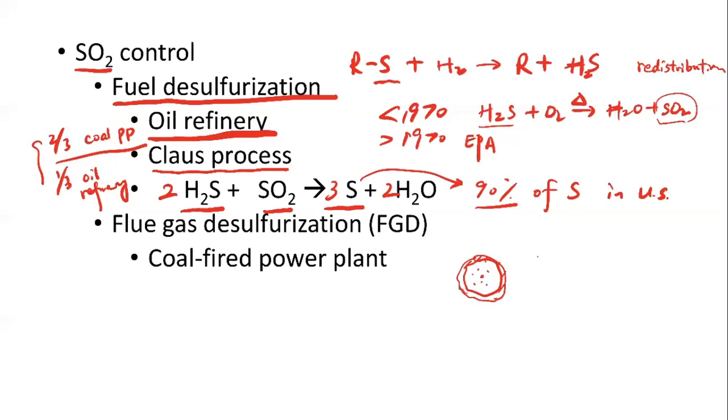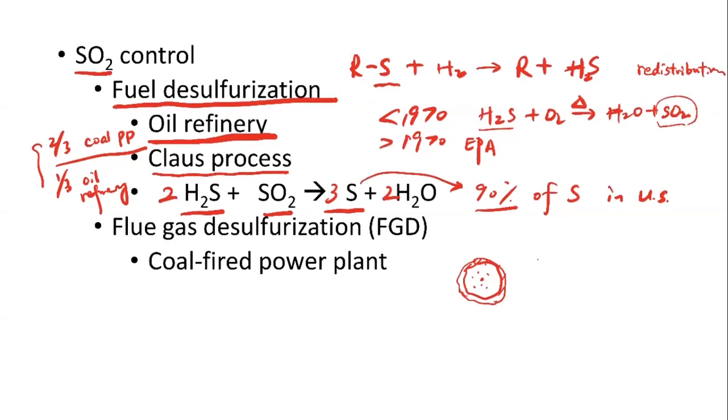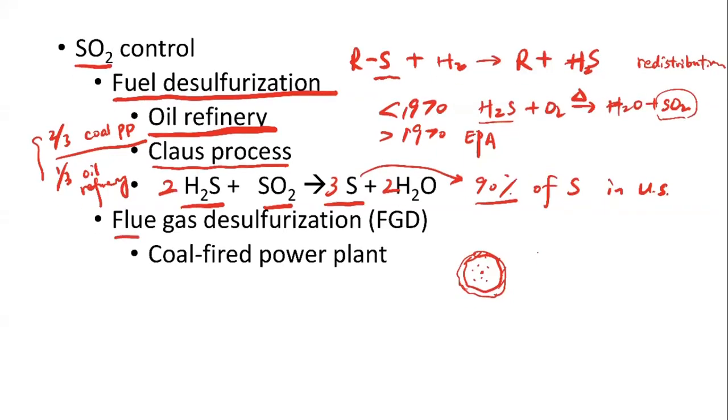So because of that, we have to deal with the sulfur after the combustion. And that is why we need to use a process that's called the flue gas desulfurization. Okay. So the flue gas is basically the product coming out of the coal combustion, right? It's going to contain carbon dioxide, water vapor, right? And always when we combust coal, we'll feed in extra air, right? Because we want to completely use the energy out of the coal particles.